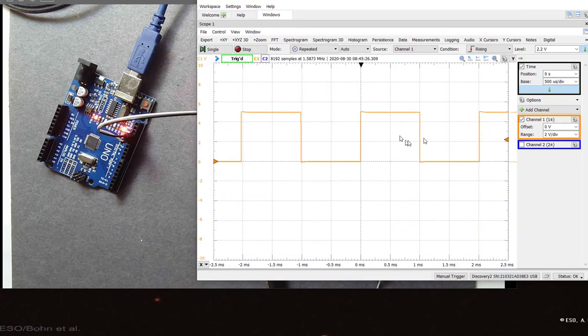And sure enough, here's the scope setup. I'm triggering on, let's see, I'm doing auto. I got channel 1 coming in. That's my source. I'm triggering the rising edge, and here's my trigger level. Nice, beautiful, wonderful looking signal. Exactly what I expect to see.